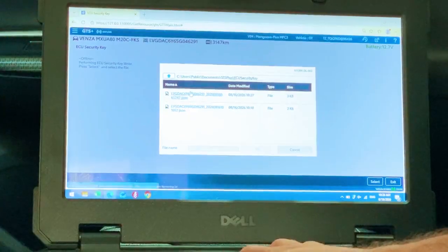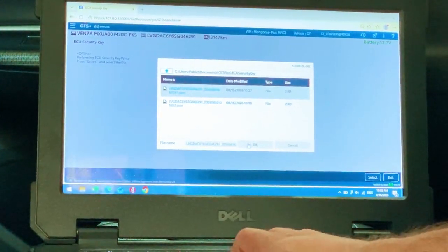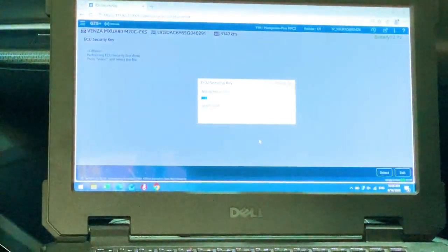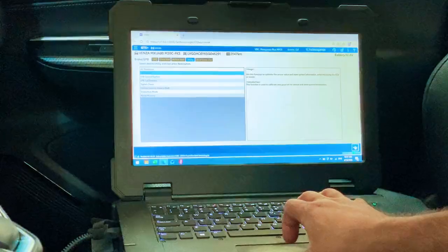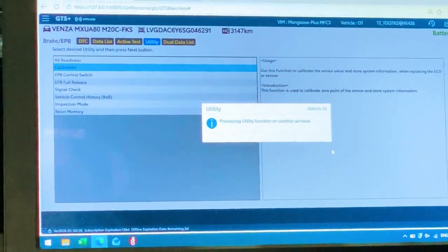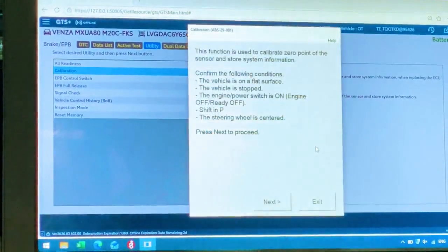After bleeding, carefully inspect every brake line connection. There must be no brake fluid leakage. The brake pedal should also have the correct feel before the vehicle is returned to service.